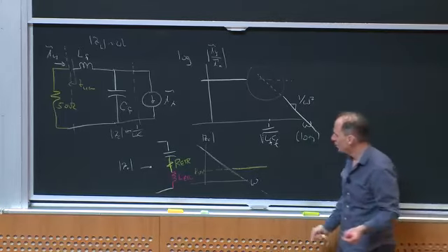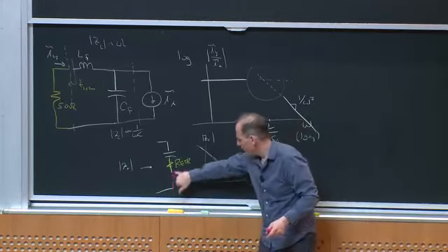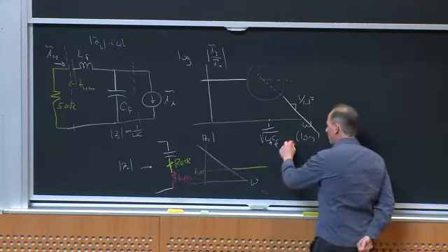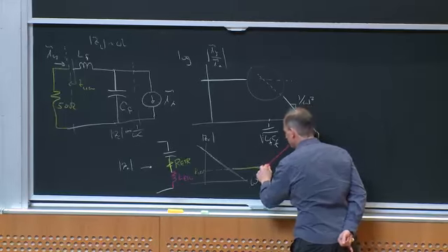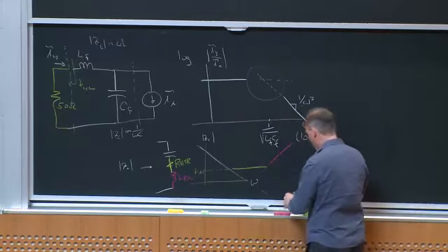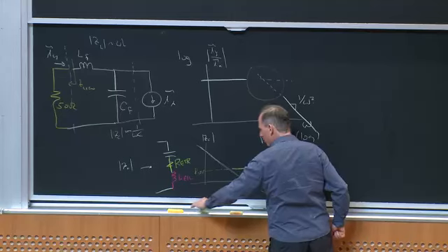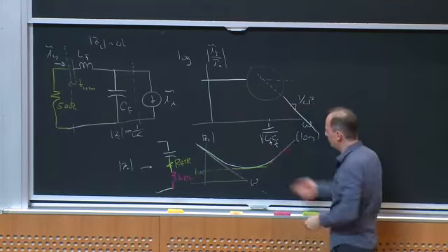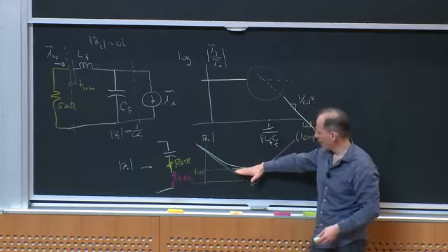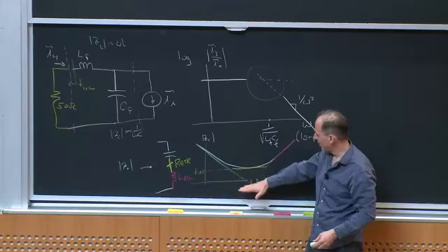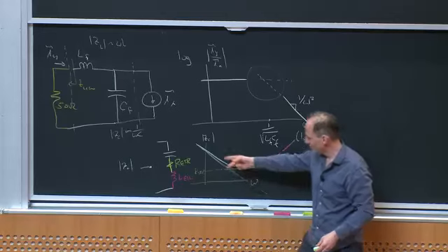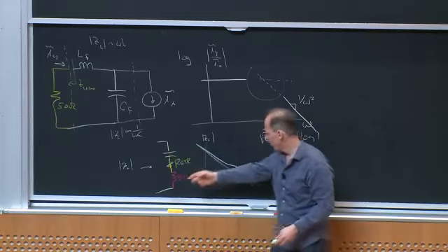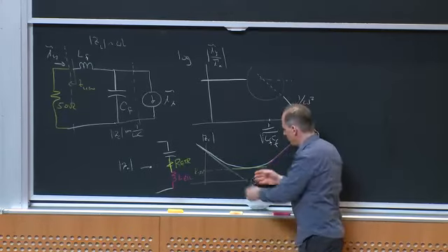So at some point this ESL will get to have a high impedance, because this is growing with omega, so it's going to go up. So my overall impedance contour doesn't fall forever, but rather it falls, flattens out, and goes up. And maybe I've shown you a high ESR capacitor. Depending upon whether the ESR is greater or less than the square root of L over C, ESL over C, this will be very sharply tuned or very broad.